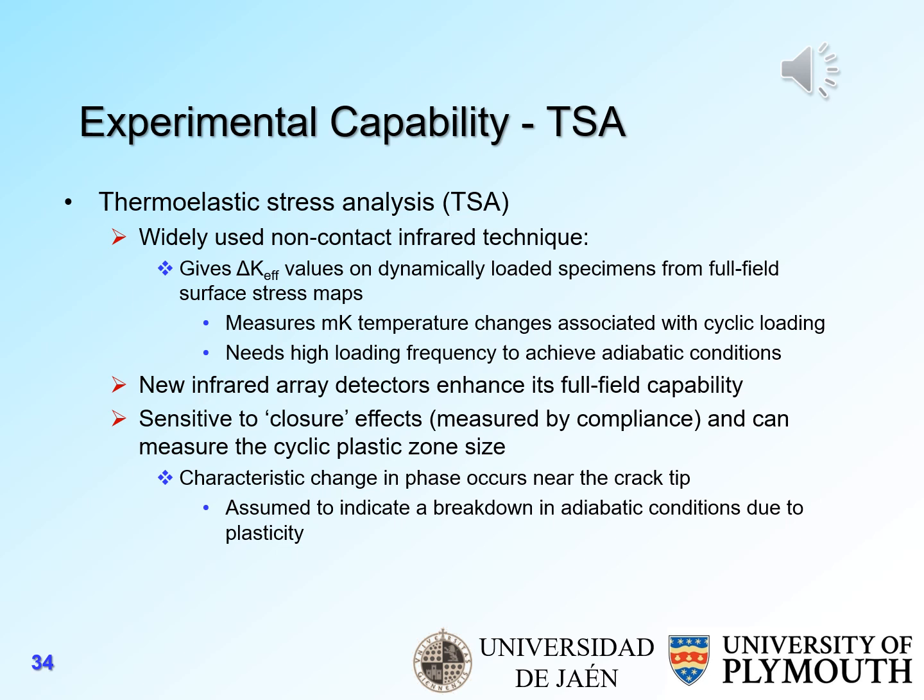And new infrared array detectors enhance its full field capability. It's supposed to be sensitive to closure effects, as measured by compliance, and can measure the cyclic plastic zone size, because there is a characteristic change in phase that occurs near the crack tip, which is assumed to indicate a breakdown in adiabatic conditions due to crack tip plasticity.